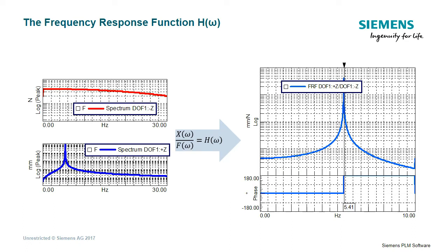This is one of the reasons why we perform modal analysis. We want to understand where the resonance frequencies are to make sure that we avoid excitation at those frequencies during operation. In the system we analyzed, an impulsive excitation would cause the system to continue to vibrate for an infinite amount of time. Also, the amplification factor at resonance would go to infinity. In real systems, obviously, there are forms of dissipation of energy, and this will change the frequency response characteristic of our system.